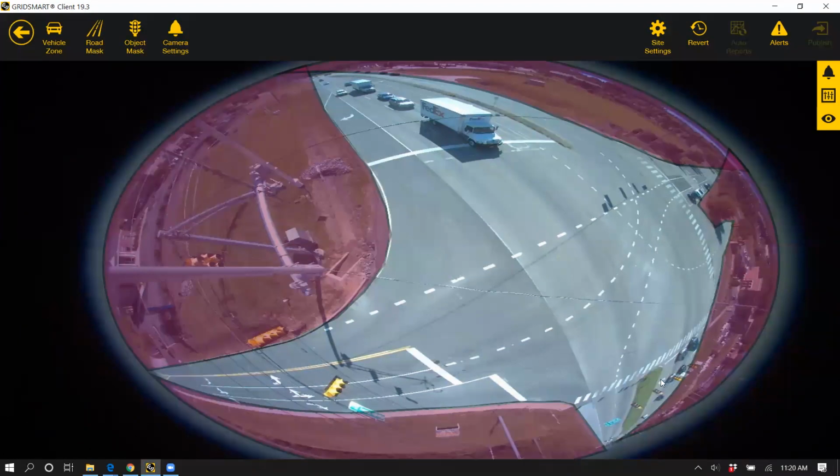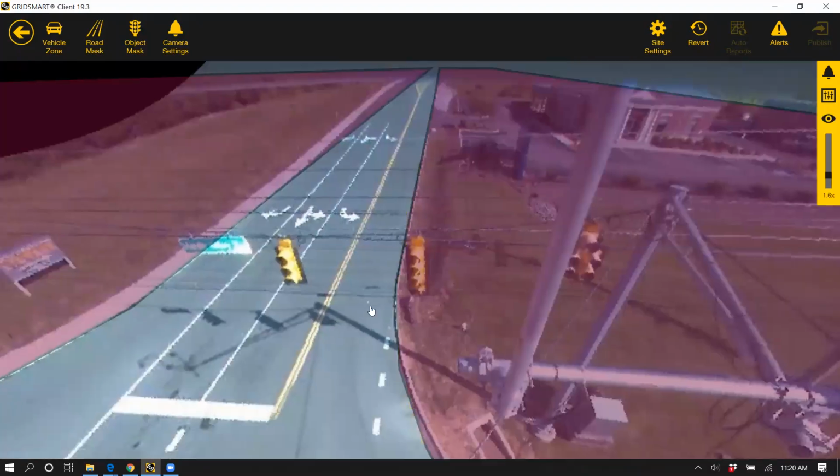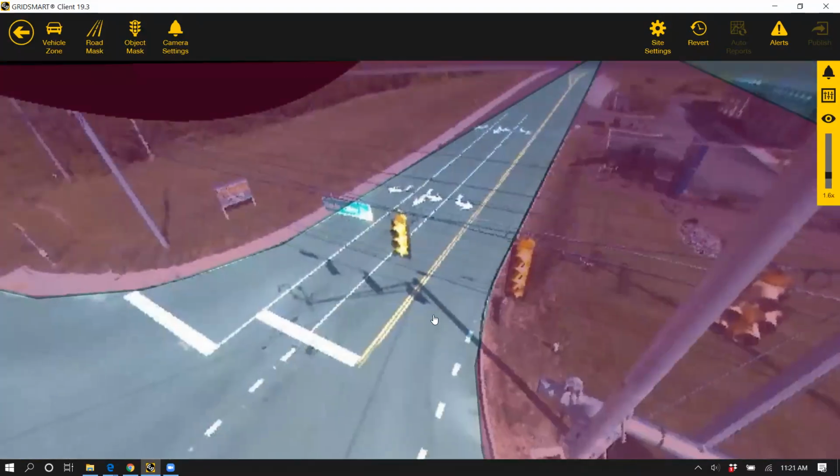sometimes you've got a B pole that comes off these medians that you might need to mask off the signal head. Sometimes there's signs, no U-turn signs, that may obstruct a partial part of your left-hand turn zone. So this sign right here, it's not obstructing any detection zones. So this is not actually a factor here, but these ones would. So I flatten this out, I pick an approach, and then we'll go from here.